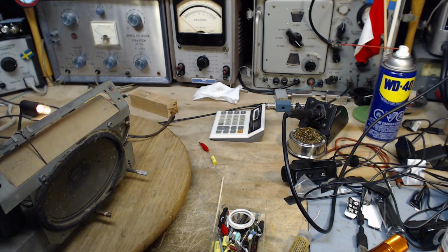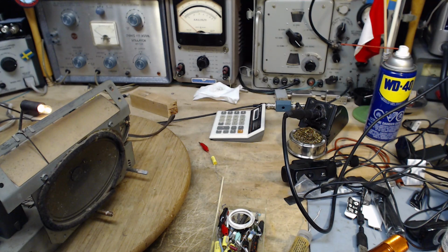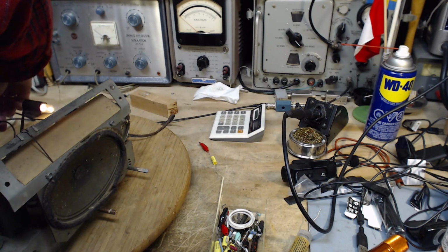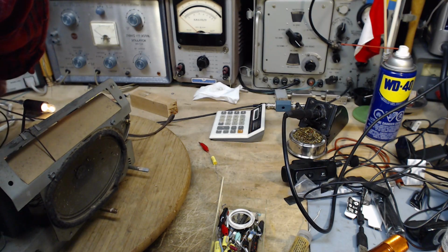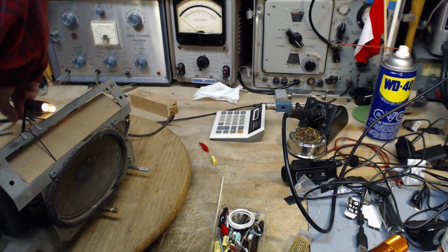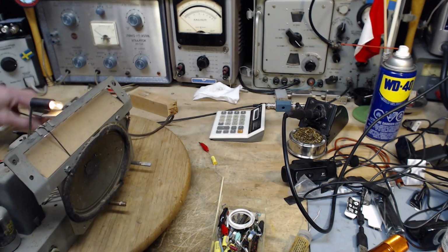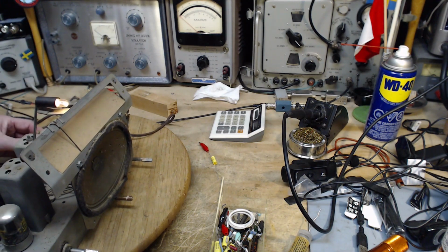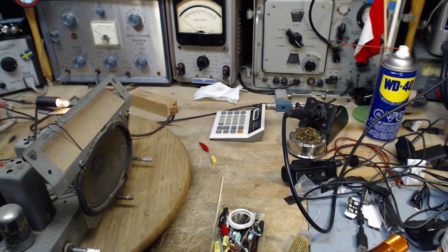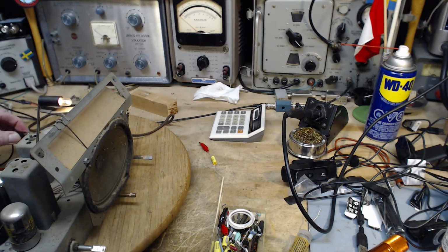Oh boy, what should I do here? This is another ground. All grounds have got to go to the same place. So I think I'm going to have to ground it onto the B minus, but that's not proper for the antenna. So we're going to take everything off the B minus connection here. I better take that off too. So now there's nothing tied to B minus. I can put the antenna on the way it's intended to go.